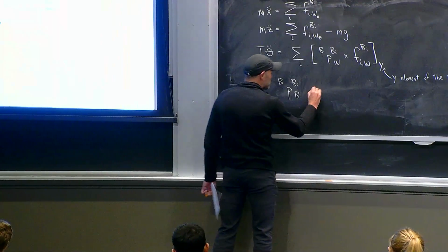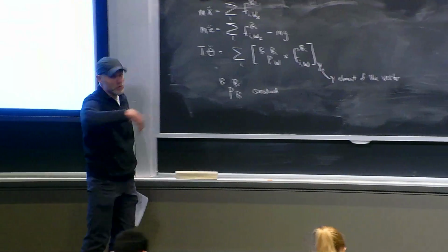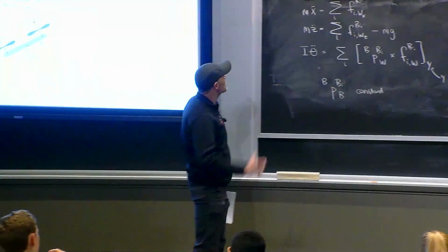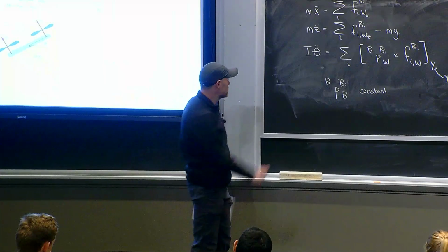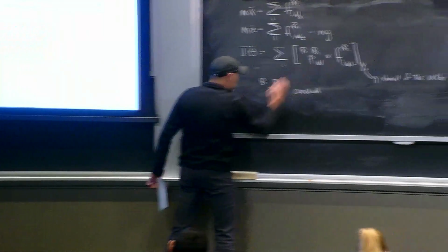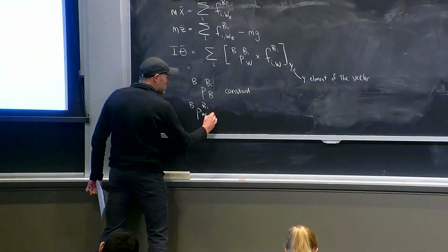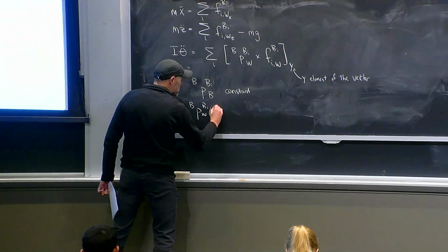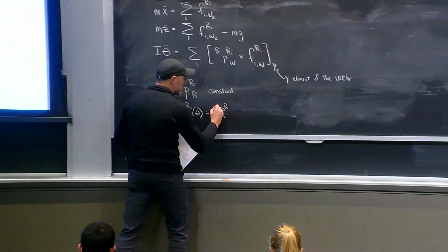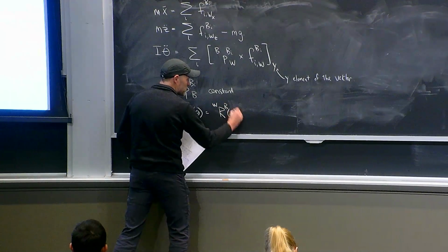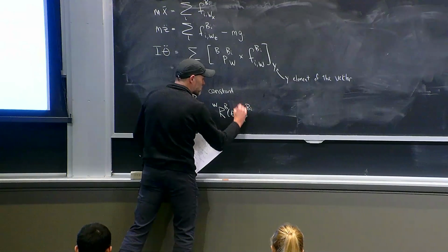This would be a constant if my thruster was in a known location on my aircraft. But since the satellite is tumbling, the position in the world frame actually depends on theta, through the rotation matrix, based on the tumbling dynamics of the satellite, of this thing that's a constant.